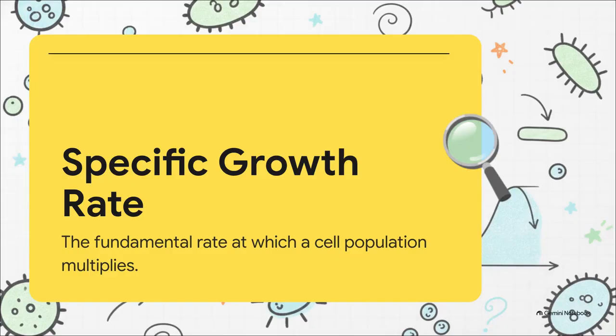Now, the absolute star of the show here is the specific growth rate, mu. The Monod equation gives us a precise mathematical link between the food available to the cells, our substrate, S, and how fast they reproduce. As the substrate increases, the growth rate increases, right up until it hits that hard biological limit of mu max. This one simple equation literally dictates everything that happens inside the vessel.